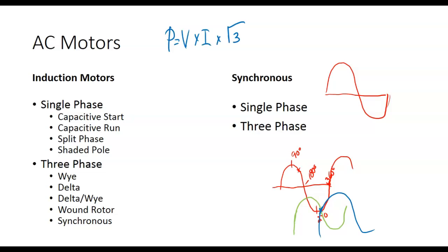But a single phase motor, if it hums at you and you spin it and it goes in whatever direction you spin it, it's a start capacitor, I guarantee you. Because what you're doing is you're stimulating the what? Yeah, the start capacitor. So if you can spin the motor and it'll come up, it'll start running in the direction that you did. That's the problem with it.